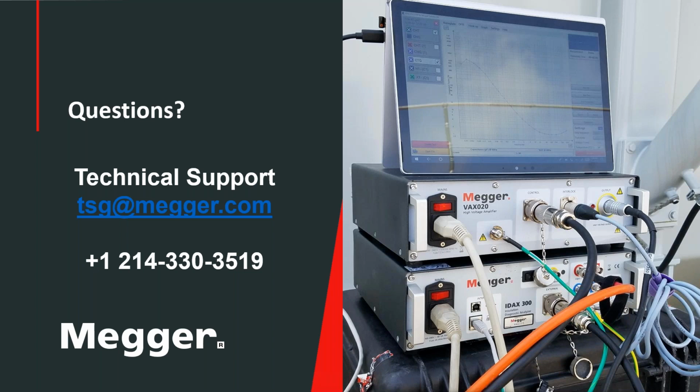All right, thank you. Dinesh, would PF measurements from Idax match the 10 kV PF measurement? That's an interesting question. Typically when you perform the test using Idax, the DFR measurement also gives you the 60 hertz power factor value, and in some other parts of the world it might be 50 hertz. The question is basically whether power factor values are voltage dependent.